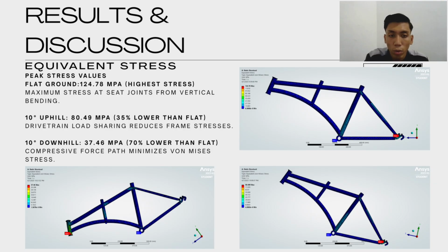Uphill conditions show a 35% reduction in stress, 80.49 megapascal, as the drivetrain shared the load more evenly.